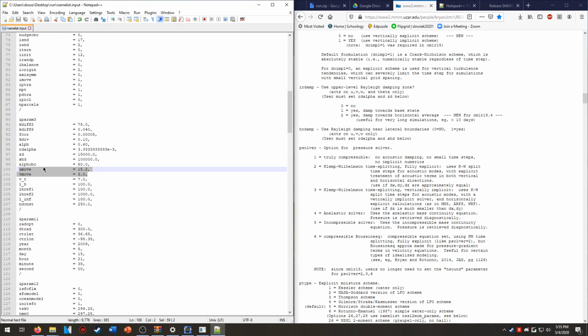Currently, the guy who actually compiled this, Anthony, is trying to develop a system that'll have the storms move directly with the domain, so you don't have to edit this, it'll just edit itself. But I always like to set a good basis. I just go 5.0 and then just 0. This is always a good way to set it. So we'll just save that. Every time you change something, make sure you save it so it'll be able to be run by CM1.